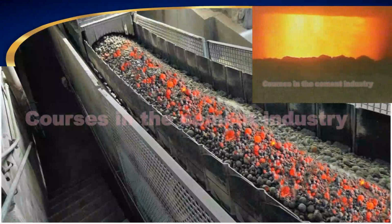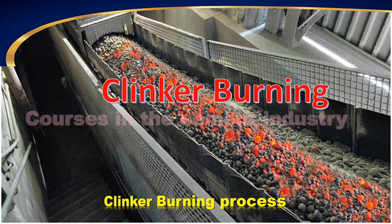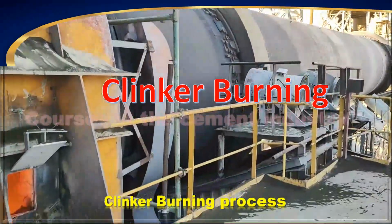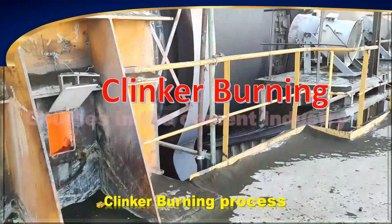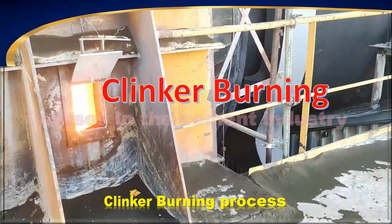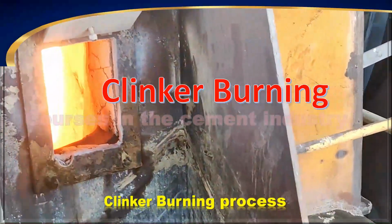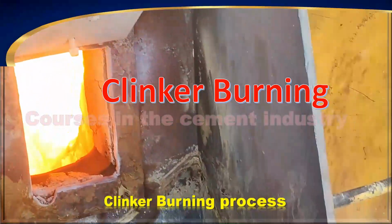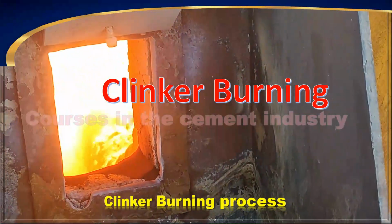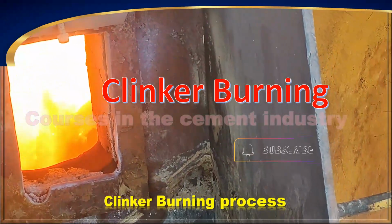In this course, we will cover everything about clinker burning. The burning process is carried out in the rotary kiln and calciner, while the raw materials are rotated at 1 to 2 rpm at its longitudinal axis. The rotary kiln is made up of steel tubes, having a diameter of 2.5 to 3 meters, and the length differs from 90 to 120 meters. The inner side of the rotary kiln is lined with refractory bricks.